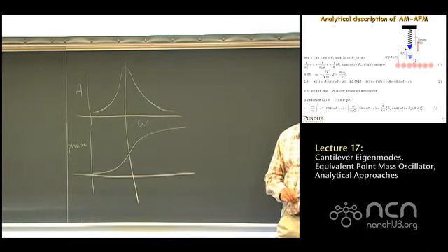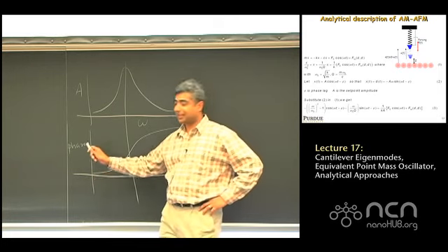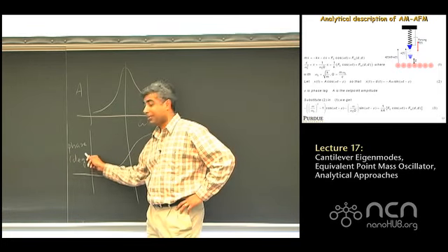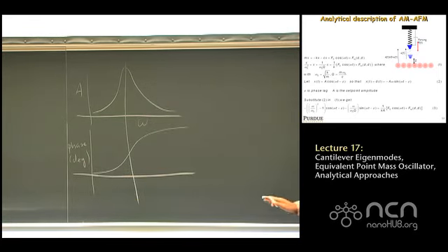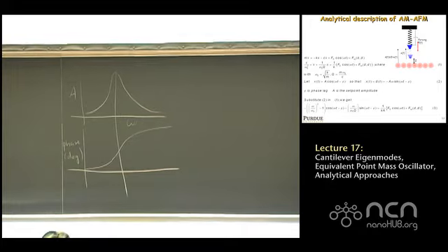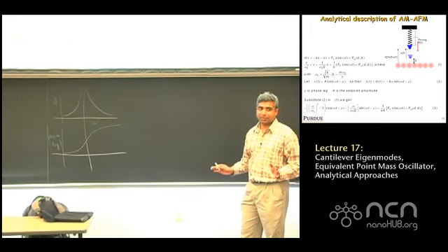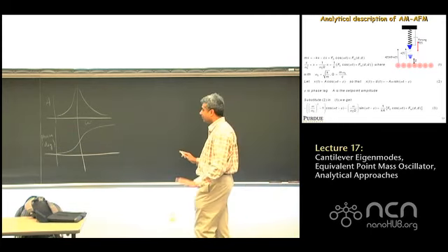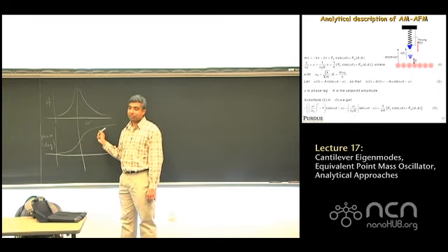right? That is, whatever number it's plotting, hopefully it's in degrees, okay? If it's in volts, again, I'm going to get very annoyed with you guys showing me these things in volts, okay? So degrees, make sure it's in degrees. Luckily, all new AFM systems automatically do it in degrees. The older ones, even the phase would be in volts, so terrible. Trying to convert that into degrees would be terrible. If it does this, what do you think it is? It's the phase lag or phase lead?